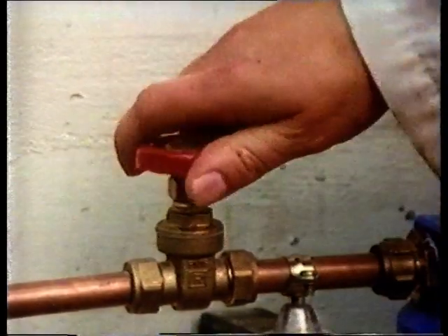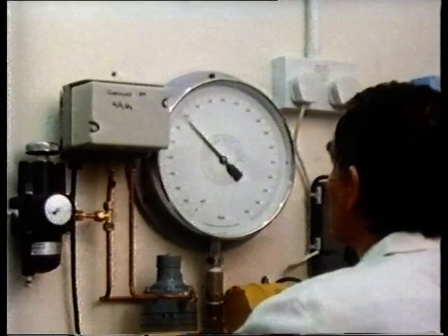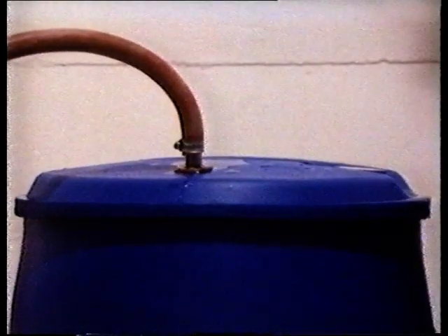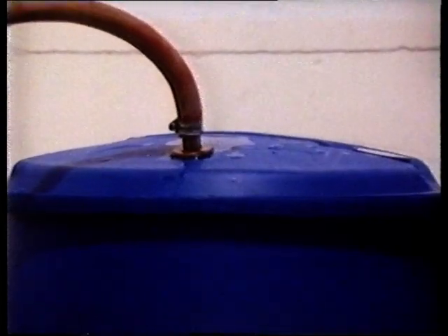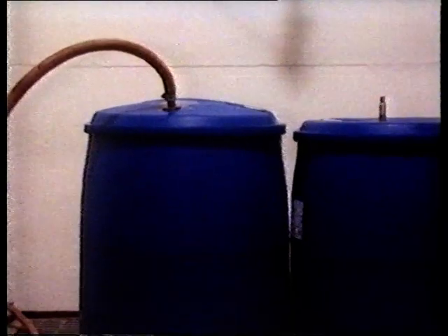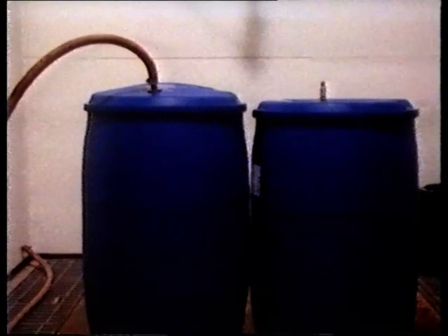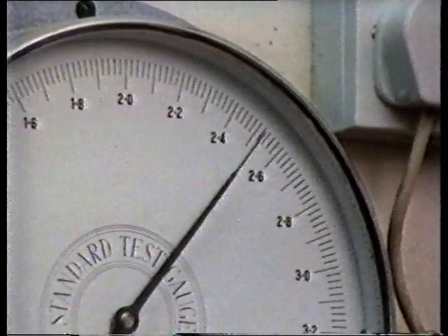Testing plastic products is very important. Here, a big polyethene barrel is filled with water under pressure to see if it leaks. Compare it with the empty one. It's being inflated by the water. When the bottom becomes rounded, it falls over, but it doesn't spring any leaks.